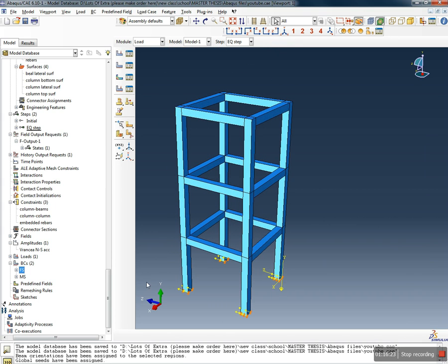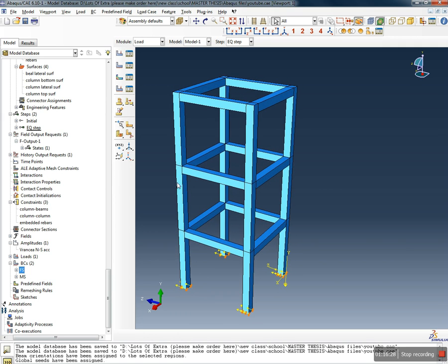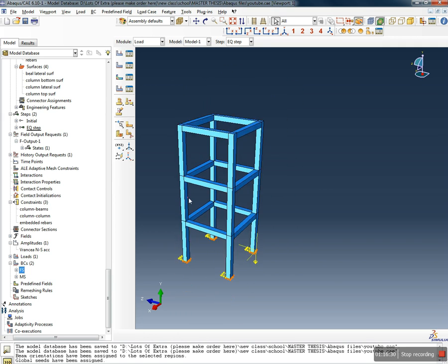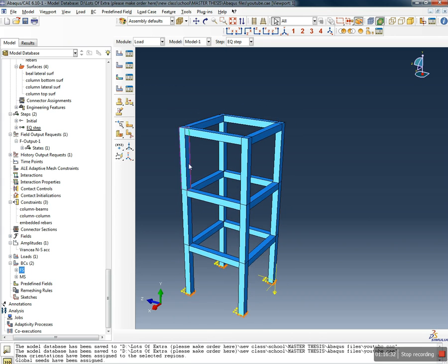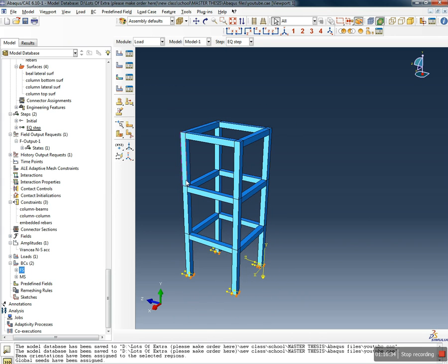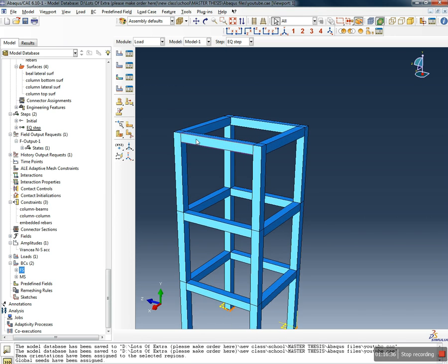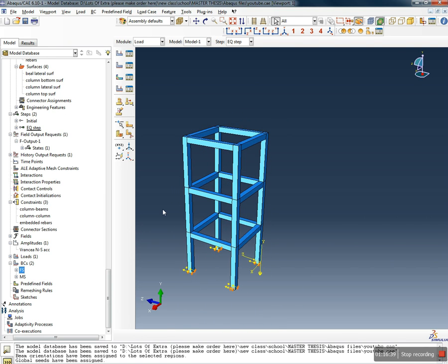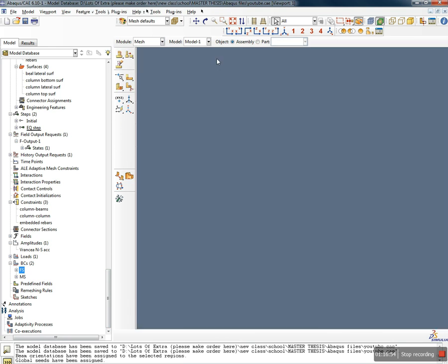So our rebars are meshed now, so we want to mesh the concrete. So what do we want to do? We want to select the whole model to mesh, or just select the concrete? Let's just select everything, because I think it's fine, because the rebars cannot be meshed with hex elements anyway, so nothing will happen.